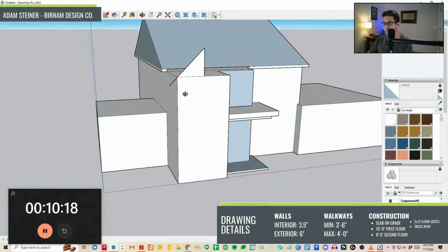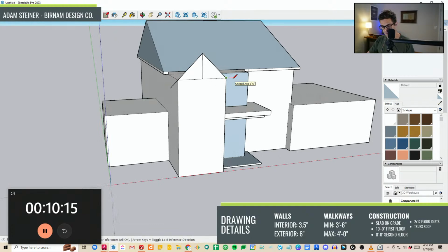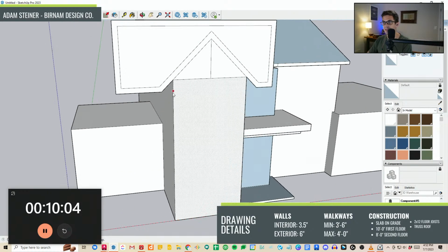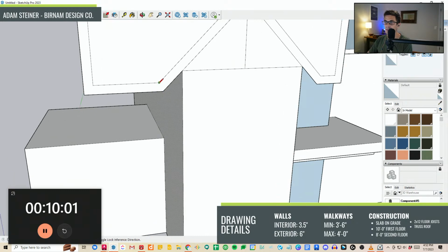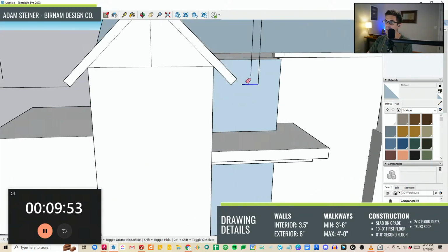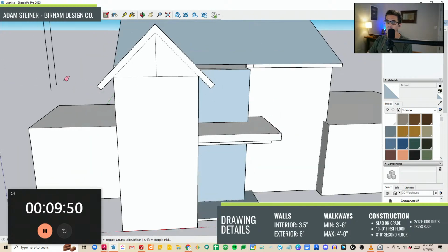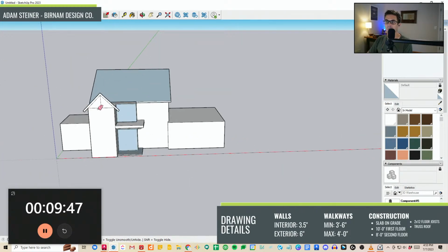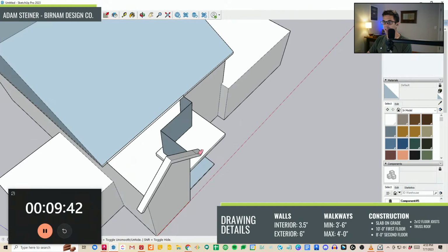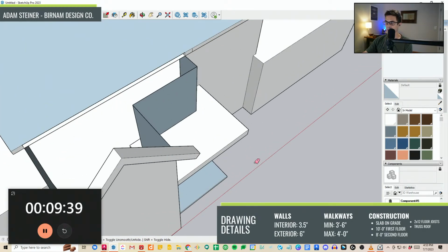Snap to that center line. And 18 and 18 again. And then if I just draw an extra face and then offset that 8 inches, it's actually a lot easier to work with than trying to do all the snaps and stuff later. Then you just come in and delete what you don't need. Boom. And then we'll come up 12. Alrighty. 10 minutes left. Drink break.